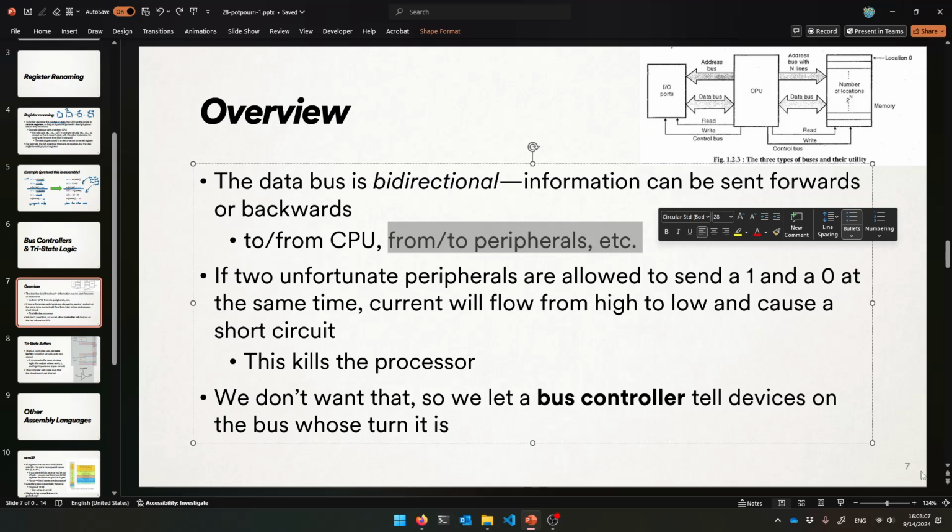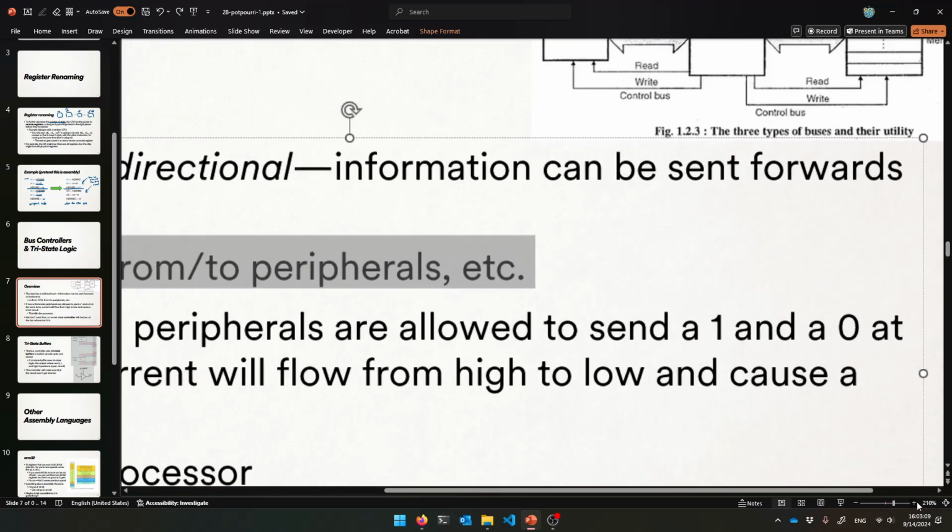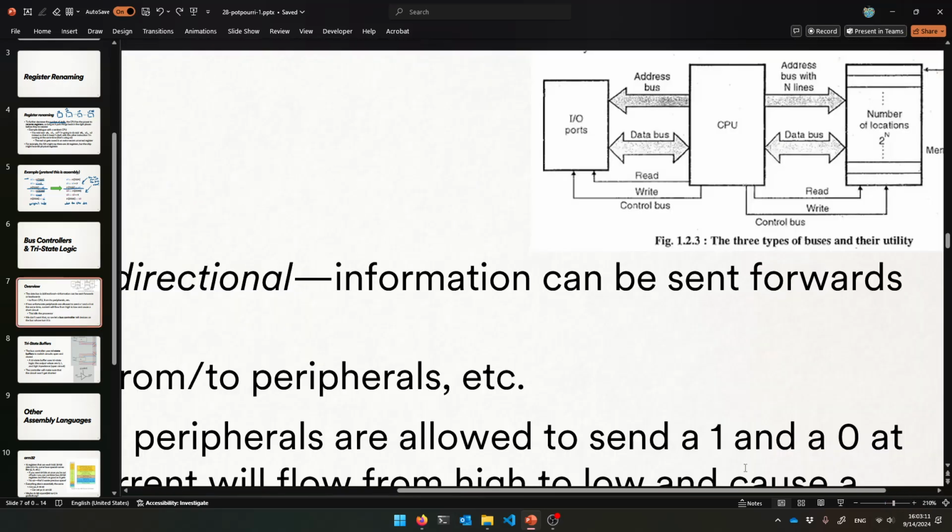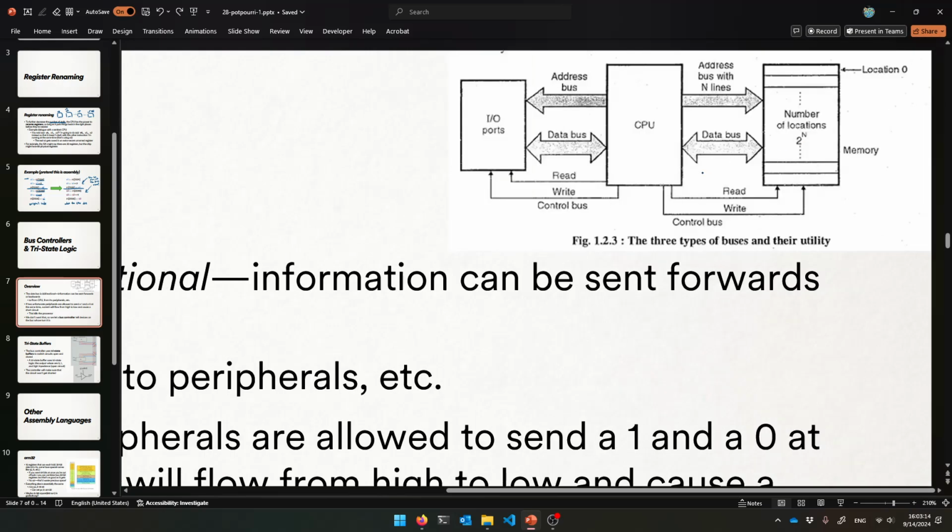All right? So you can do reads and writes, and maybe I should draw those in different colors so that we can come back and study later. So if the CPU wants to read from memory, if it wants to load, it's got a register it wants to place a value in. It sends along the address bus, hey, go to this address, please. And then the memory gets ready. It goes to that address, and it also sends a read signal. I'll give you back along the data bus my value, and it stores it in its little register. So that's like a load.